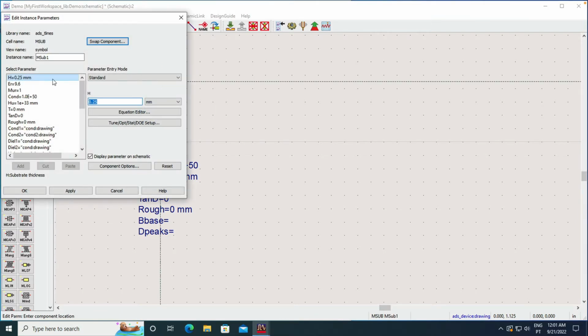In this case, we're going to change this, going to specify a height of the substrate of 0.762 millimeters, dielectric constant of 3.2, conductivity I'm not going to change, and the loss specified by the tangent of delta, we're going to provide a value of 0.003, which means that there will be some loss of the line with increasing size.